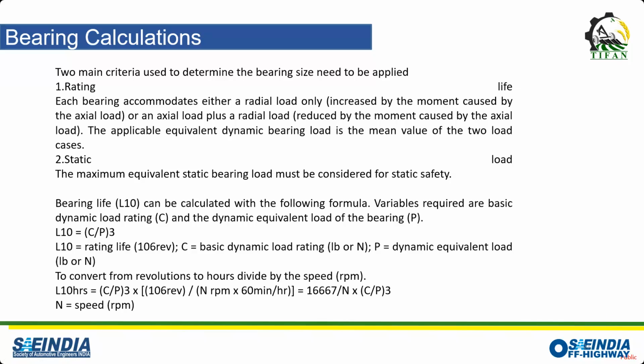Why you need them is because once you have this load data, you can directly go into the supplier's website, put in these values, and then a recommended bearing type may appear, and then you can go and buy that bearing. Or you can even just give these dimensions in the market, and you will be given some suggestions for which kind of bearing you can use.